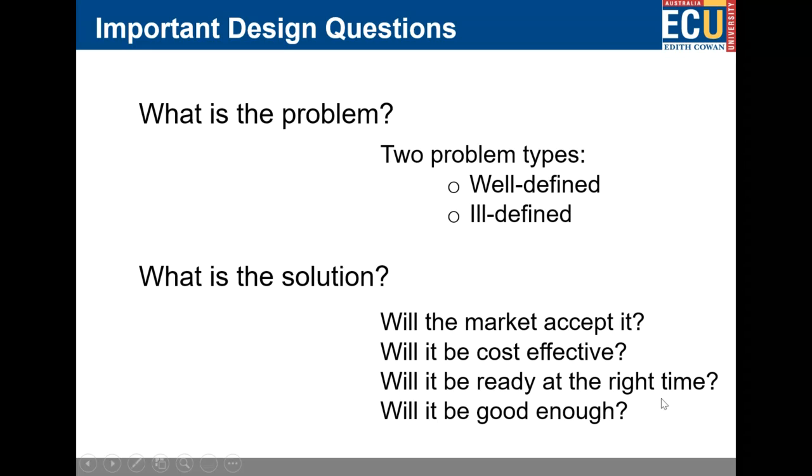Can you find what's wrong with it? Okay, and it's quite easy. You can have a look at what loads are going in, what loads are going out. You can find out what size of gearing is, etc., to calculate some loads, and you can actually then calculate what the expected life is, and you can then resize it. Okay, very easy to do. It's like it was put into an equation.